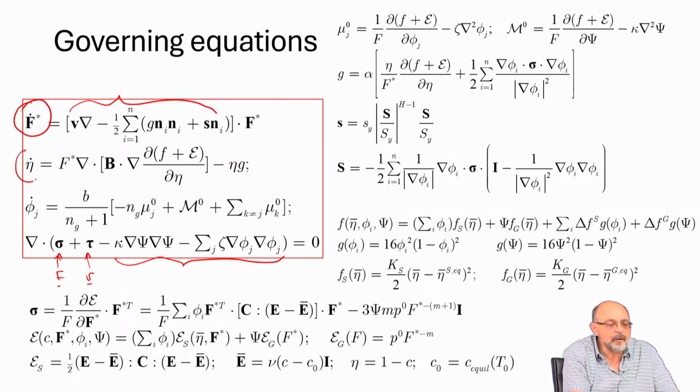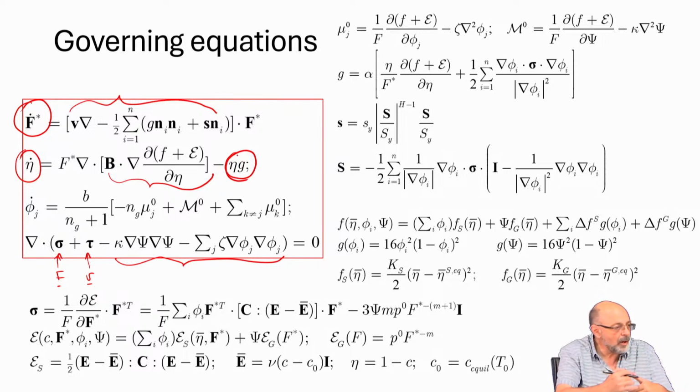Evolution of my diffusion variable has a gradient, a divergence of a flux, and it has a sink term. This is lattice growth, the sink of mass, right? You need a sink of atoms, because you need to put atoms into the mass, into new lattice.